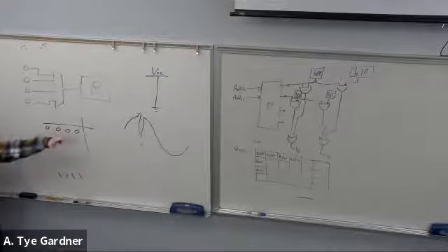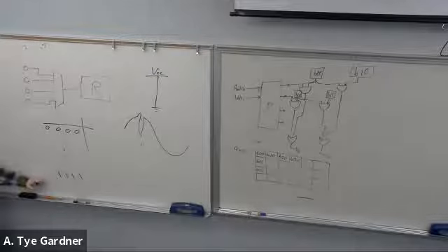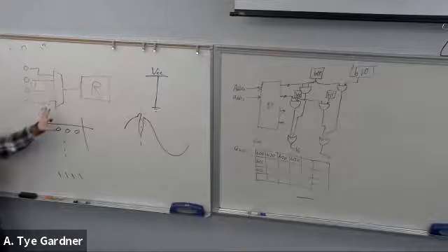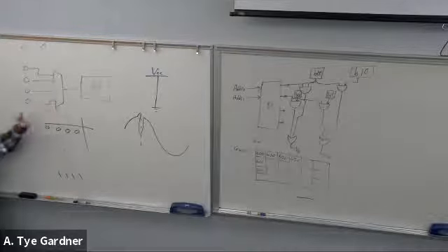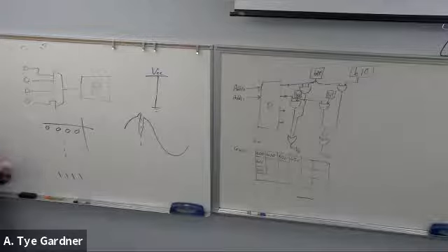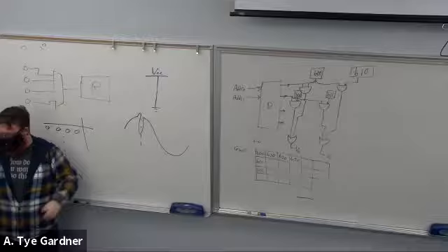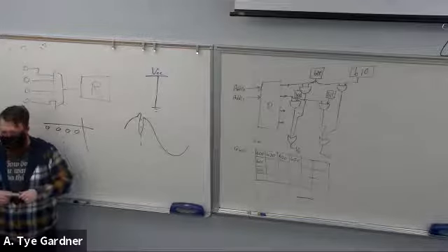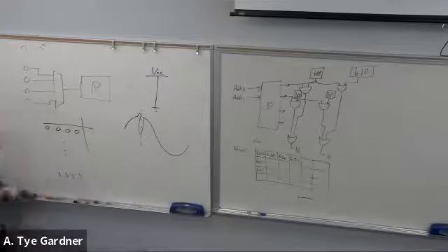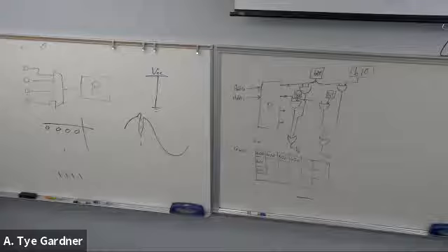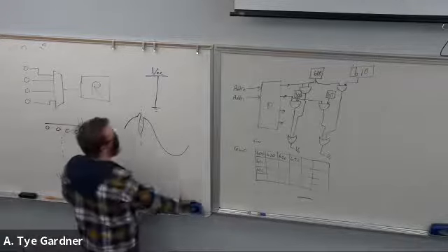The same problem can happen. Gray code can fix that in this circuit, because it makes it so that only 1 bit ever changes, right? That's the logic adjacency. We save exactly 1 bit. We don't have the issue, and I never get these massive spikes. Instead, I get these little tiny ones that are pretty easy to deal with. So there's a real world example of both muxes and gray code, and why we would use them.